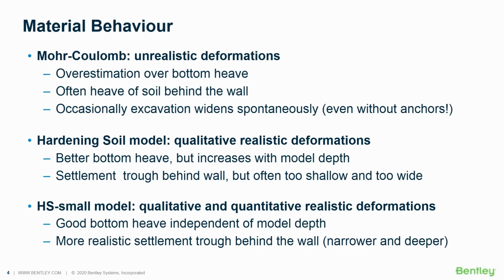The reason for that is that the Mohr-Coulomb model, inside the Mohr-Coulomb failure surface, deals with every stress path as an elastic stress path. So unloading and reloading are always considered with the same stiffnesses no matter what. And this is the reason why unrealistic deformations are being obtained.